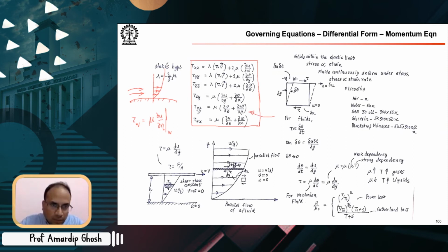So this thing is really a combination of the coefficient of viscosity multiplied by the summation of these two velocity gradients. On the other hand, for parallel flow, where you don't have significant gradients in the other components of velocity, sometimes you see a form like this. Although you see a form like this, you have to keep in mind that the generic forms are actually this. And where do we get these generic forms?